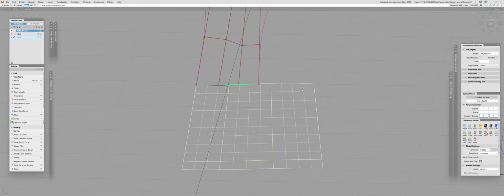And these isoparms are just a visual representation, as I said, of the domain of parameters of the surface. On these intersections, you can think about them as points. So every intersection is a point, and there is a grid of points. You probably know that NURBS surfaces are always squared surfaces, and they have the domain of parameters which define their shape. And the isoparms just visually show you this domain of values. And as I said, these are points. Technically, these are not points. This is a t parameter, just a variable which you can change in the polynomial equation, which basically creates the surface.